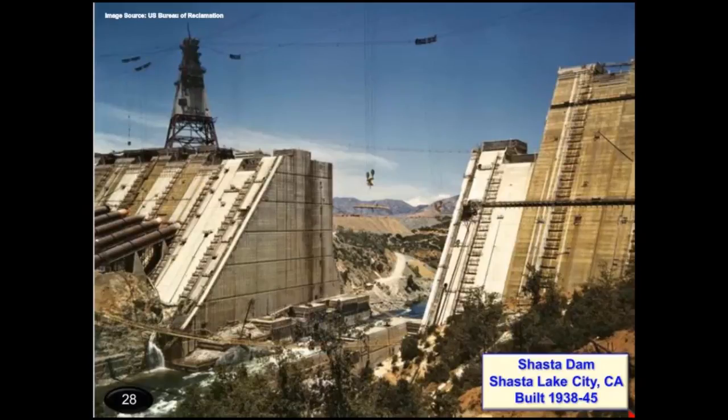Here's a good example of a big concrete dam under construction, and you can see a cross-section of the dam here. And in this case is a concrete gravity dam. It's solid concrete, and most concrete dams are built on a rock foundation. They're not built on overburden because they have a very small footprint, often less than a third of what would be the footprint required for an earth embankment dam. And that's, you can have very high flow gradients underneath, and that's why it has to be on a rock foundation.